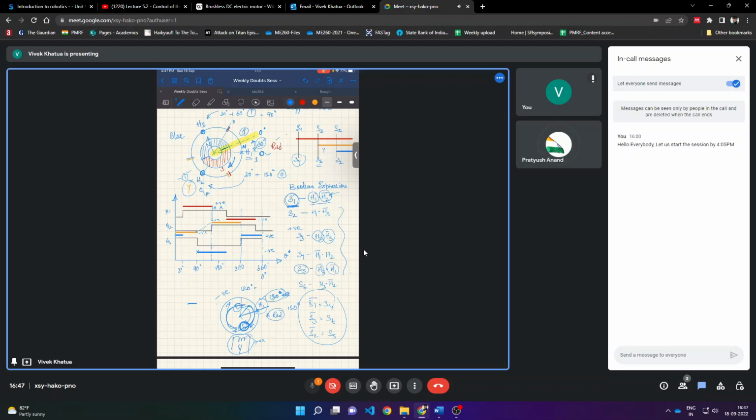So that is the physical limitation. You can have multiple hall sensors, but they are not going to help you. It's going to be the same because the period is reduced. Now it is 0 to 360. It will reduce to 0 to 120 if you double the number of poles or triple. Sorry.